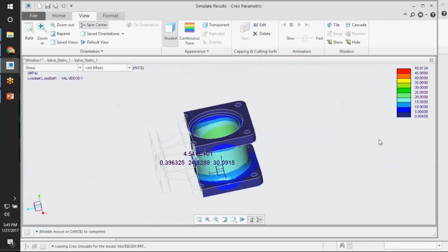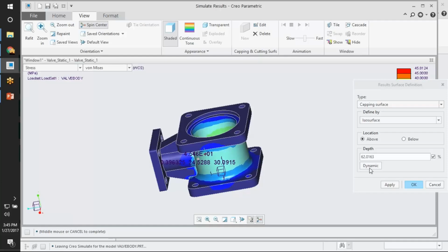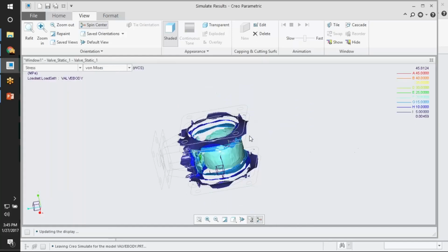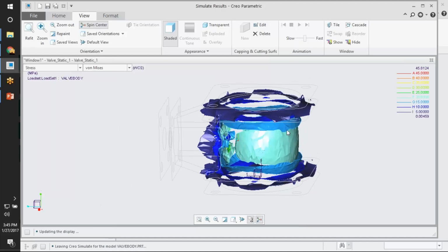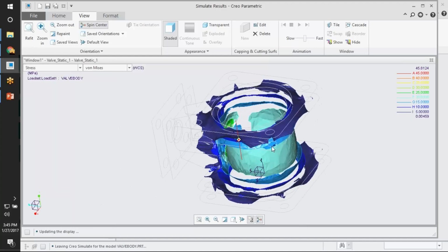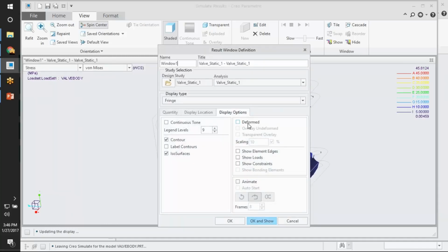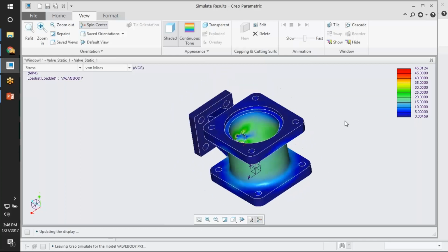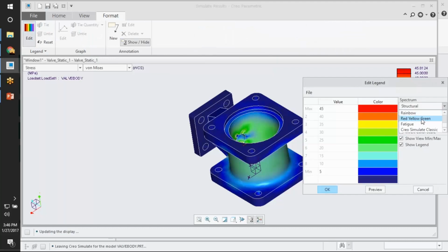And where are the high stress regions? Directly, if you want the high stress regions, go and click the isosurface. I'm just going with isosurface. So these are the high stress regions. So straightaway you can come to a conclusion that these are all the places affected by the load. And these are all the places where I have very negligible stresses. So straightaway you can perform that. It's a continuous tone we have, and we have various spectrums of outputs, various scales.